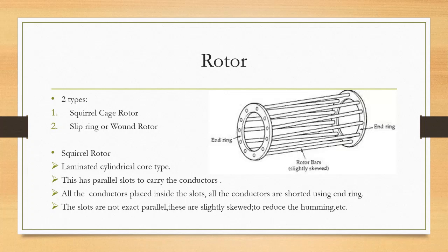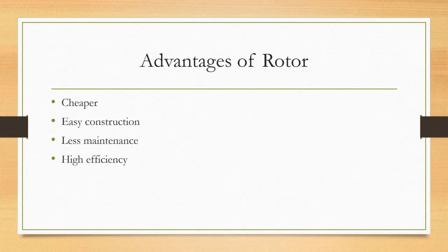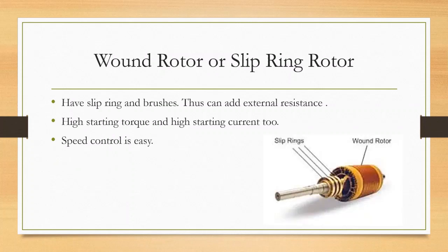The slots are not exactly parallel. So you can see this in this diagram. These are slightly skewed to reduce the humming and noise. Next we will see the advantages of this rotor. This is cheaper, easy construction, and maintenance cost is very less, and high efficiency also.